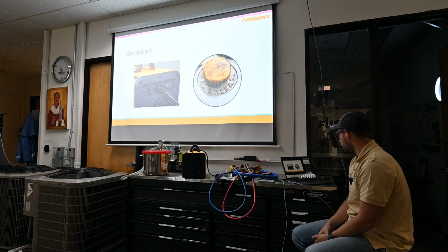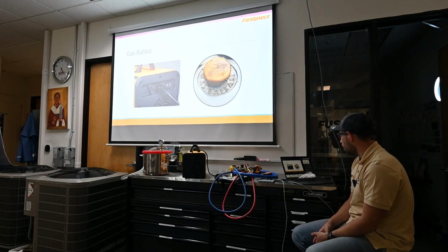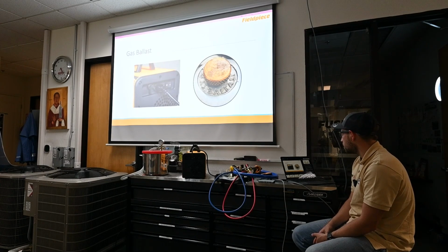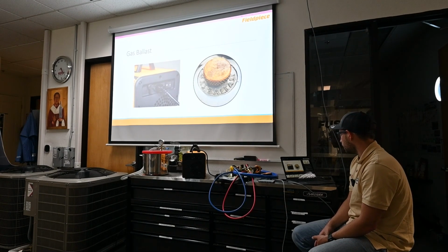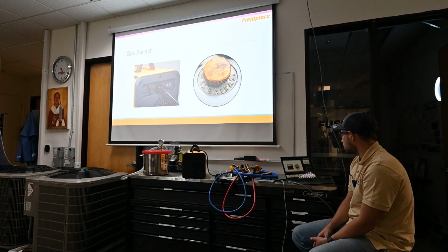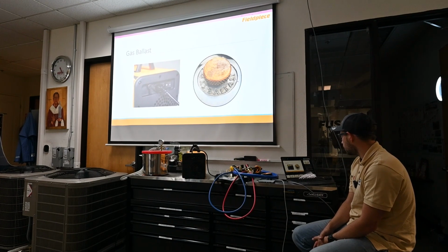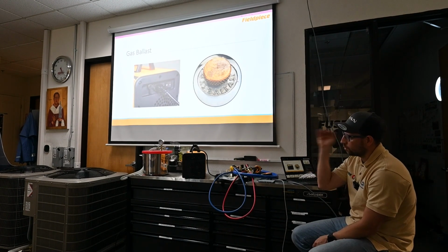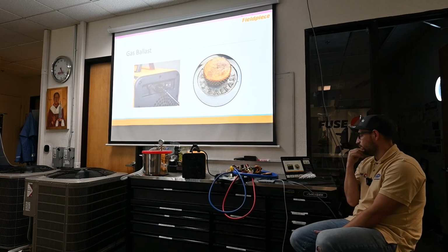When moisture vapor stops coming out of the exhaust, or at about 3000 microns, whatever comes first, close the gas ballast valve. If the system is dry, use of the gas ballast is not necessary to reach the desired vacuum level. The Fieldpiece gas ballast is much easier to use than the old style pump.